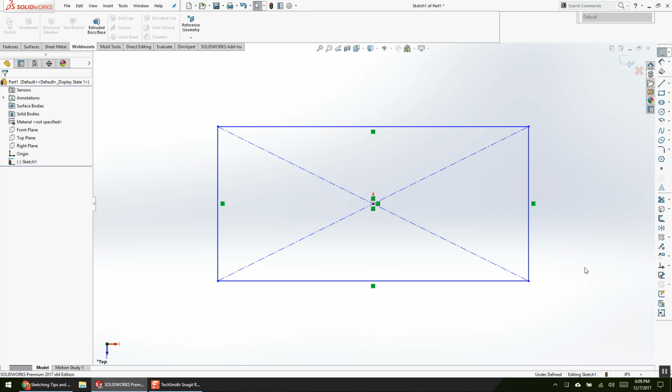That's in the next section. But planes are incredibly reliable unless I delete a part. So if I have a part in an assembly and I mate to that plane, unless I delete the part, will that mate ever fail? No, because I cannot delete my planes. So in the ecosystem of a part file, your plane is the most reliable thing in the world. Nothing will make that plane blow up because that plane is undeletable. It is the absolute base foundation of our 3D parametric model.